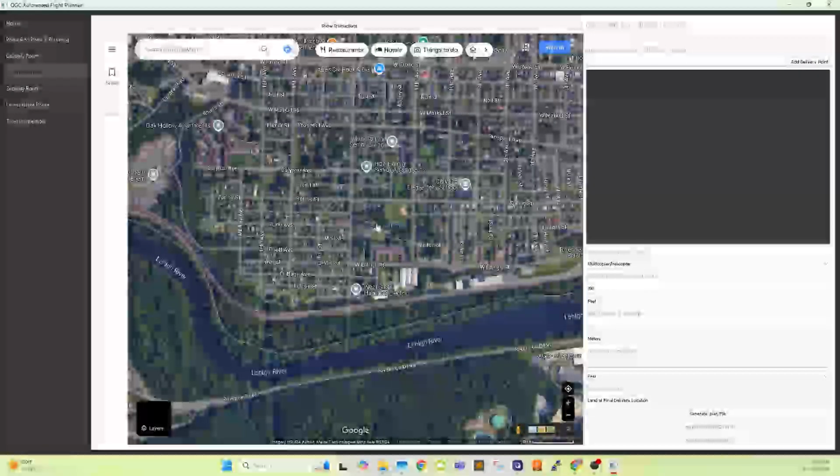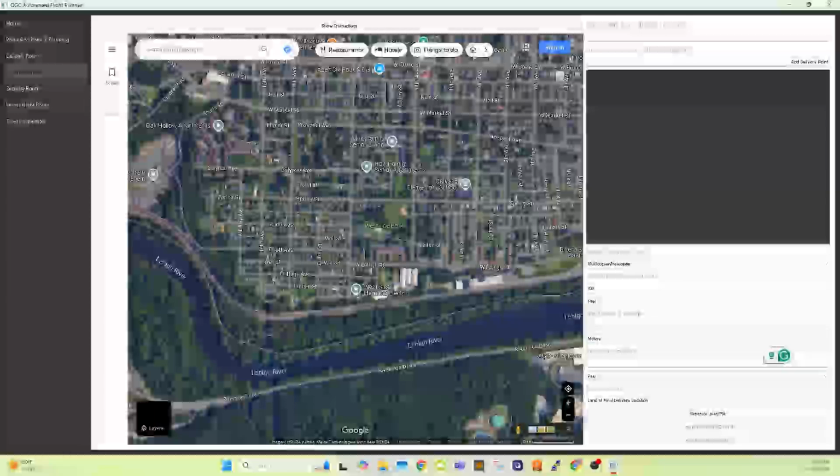But if you're flying in a highly metropolitan area, you want to double check your altitudes and maybe just set it higher to be safer. Now, waypoint intervals, of course, we can change these from meters to feet, and we can set that to 500, so that every 500 feet we have the most accurate terrain elevation changes for our waypoints. But if you're dealing with a location that has what you may see as a more rapid elevation change, you may want to shorten that waypoint interval.